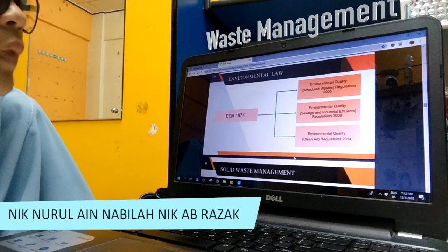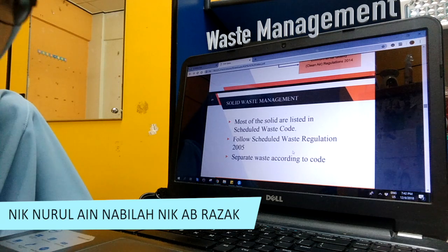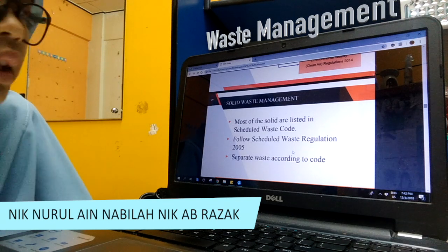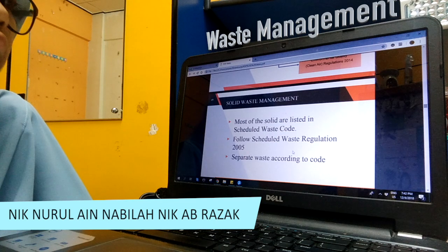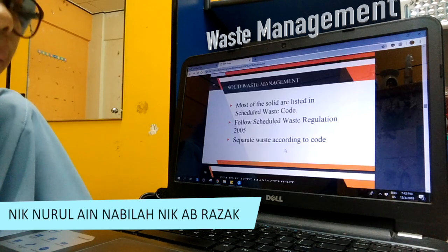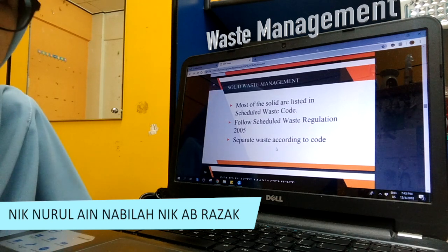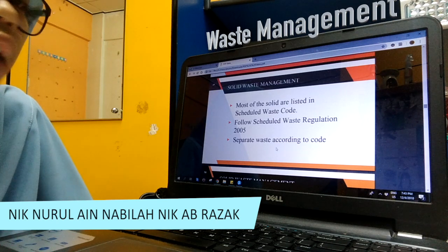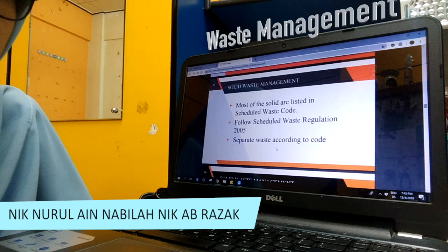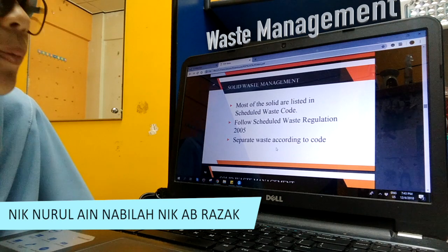from our plant. So for solid waste management, most of the solid waste that we have in our plant is listed in the scheduled waste code, and we follow and comply with the Scheduled Waste Regulations 2005. Before we dispose to the prescribed premise, we have to separate the waste according to their code, and then we will send it to the prescribed premise for further treatment and disposal.